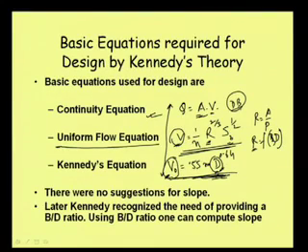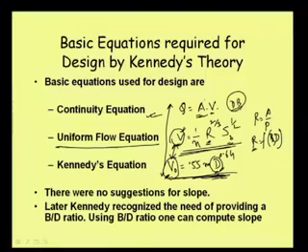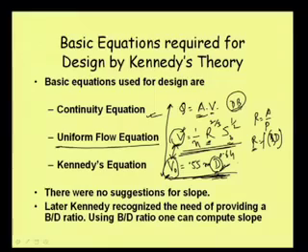But if these two velocities are not matching, that means our design is not correct. We are considering something to be the critical velocity, but in reality we are getting something else, because the flow velocity that we get by using the uniform flow formula is actually the velocity that we will get in the field. So it is not matching. That means the d we assumed initially, or rather the trial value of d that we took, is not correct. So what will we have to do? We will have to change the d value.